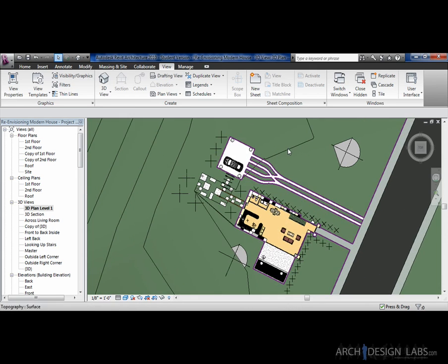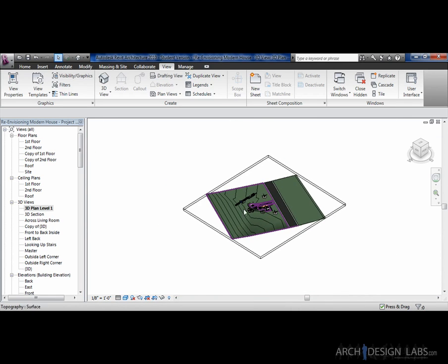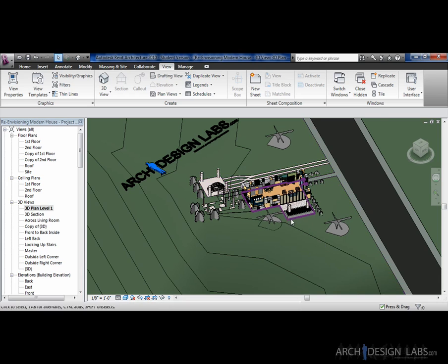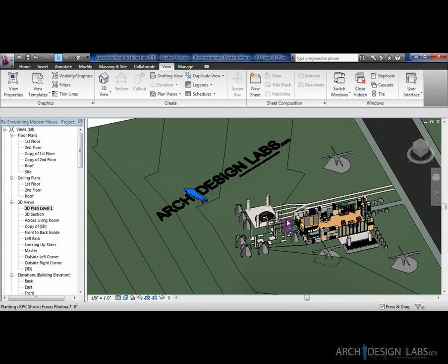And again, it just seems like a normal floor plan, except for when you go to axon view, it's actually changed to a 3D floor plan, which is really neat because if you're limited for space and you can't apply section cuts or elevations because you have a page restriction, 3D floor plans can get two points across at once. Or at a later date we'll actually show you how to create exploded axonometrics from these views saved on top of each other.